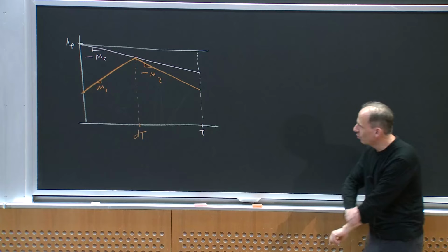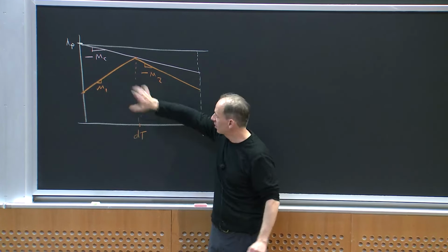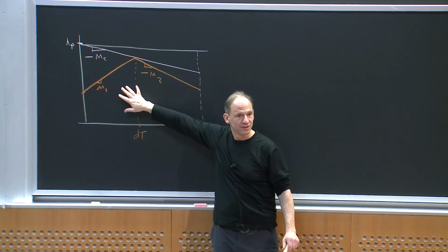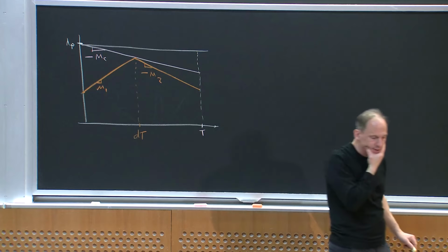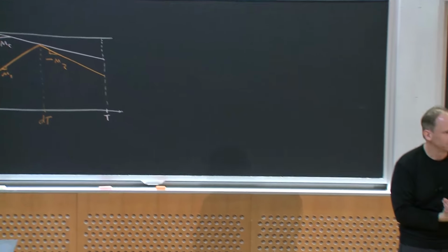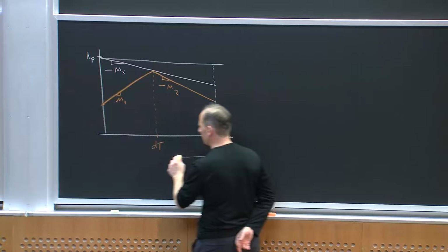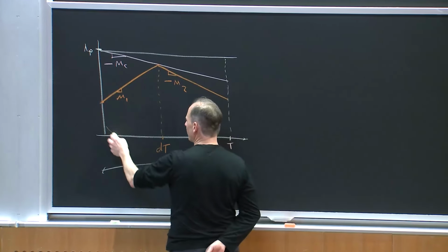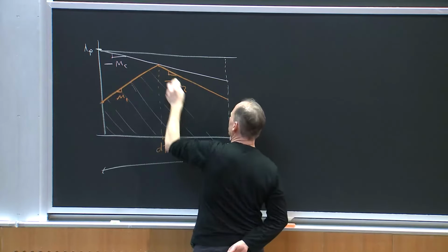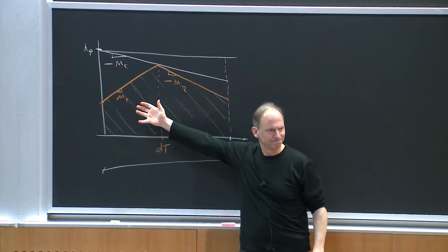And what I want to do is relate somehow this duty ratio in this cycle to what the local average of the inductor current is, okay? And I'm not going to do that by local averaging. What I'm going to do is make a geometric approximation. I'm going to say, let me look over this window, and the average of this current is the local average.